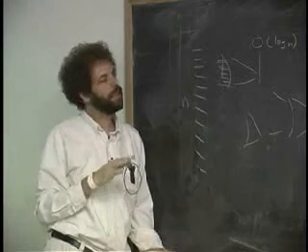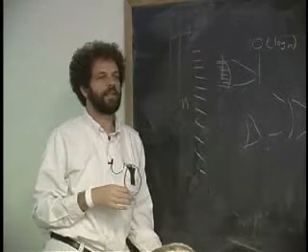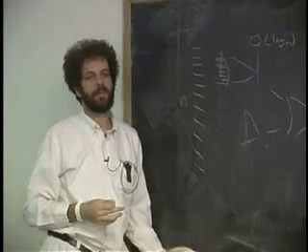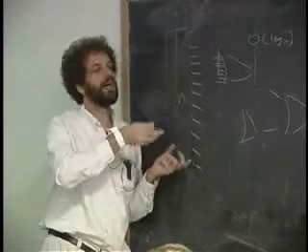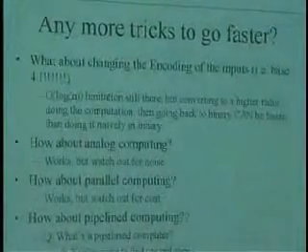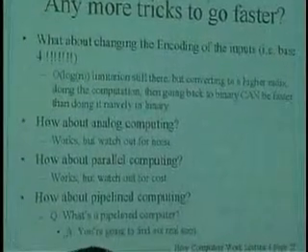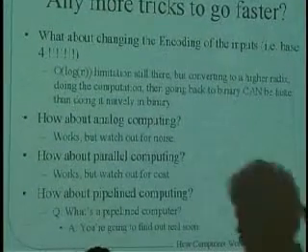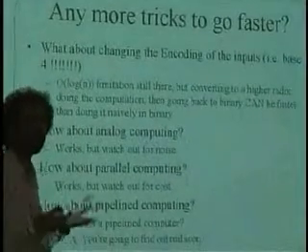But it turns out that n is usually not that big. 64, 128, it's not 10,000 bits. What that means is that usually the constant factors of the design will dominate what you in fact do. So it's basically order log n in theory, but in practice there's all kinds of tricks that you can do. I showed you the lookahead of generate and propagate. There are also other tricks where you pre-process the inputs and change what base they're in. We've been only doing things in base 2.